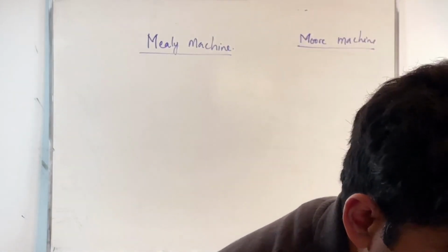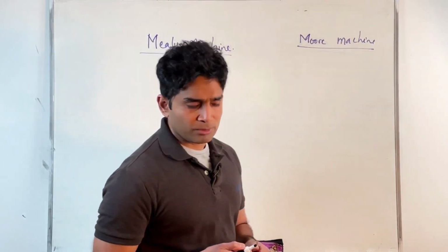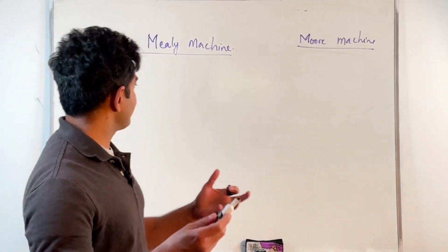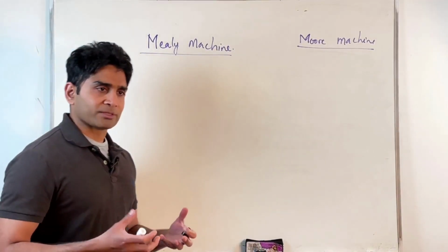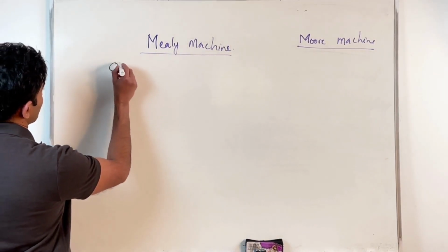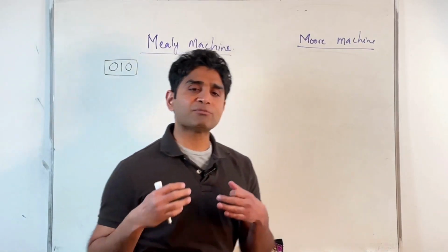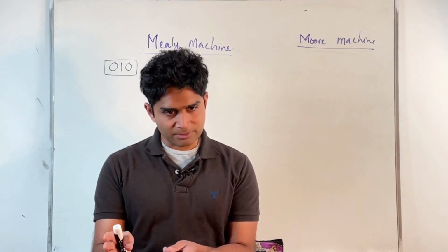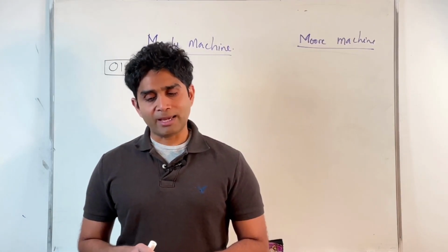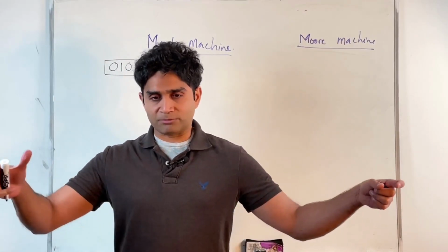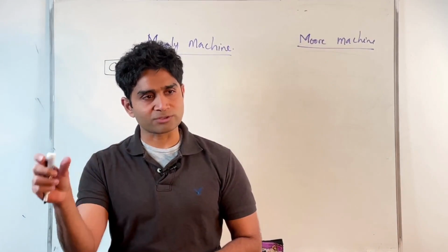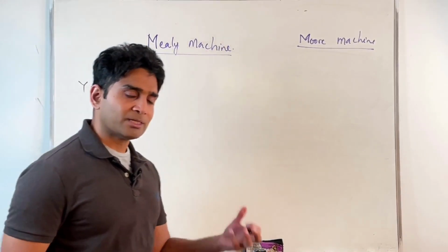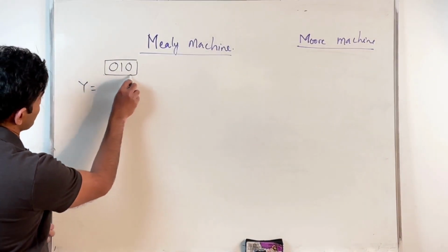All right. So Mealy and Moore. And in the last class, we also took the example of a particular application, the design of sequence detectors. We set out to design a sequential circuit that can detect a simple sequence in the input bit stream, 0, 1, 0. You have a continuous stream of bits going into your sequential machine, one bit at a time, synchronized with the clock. I want to detect that particular sequence 0, 1, 0. Every time I see the complete sequence, the circuit should output a 1.